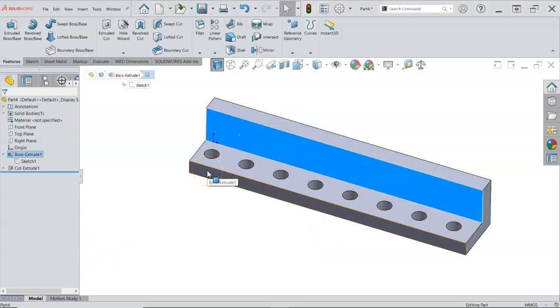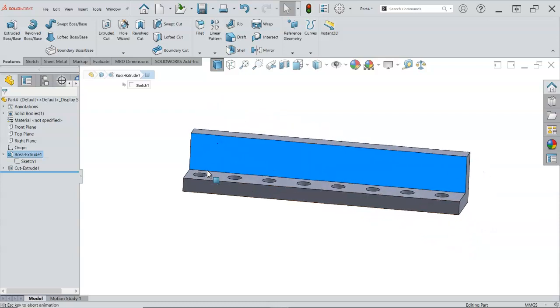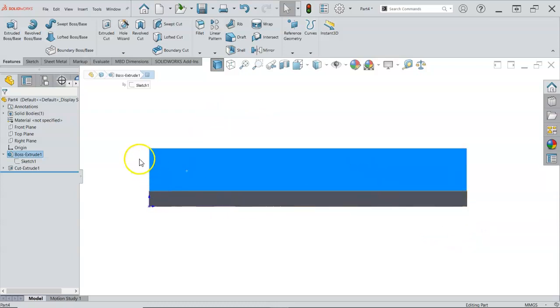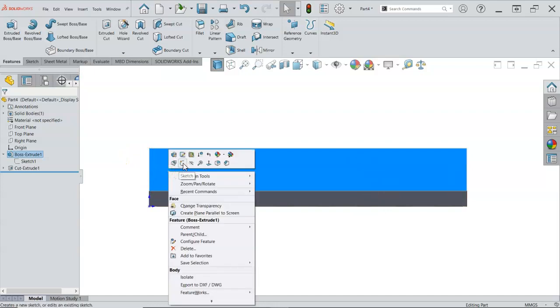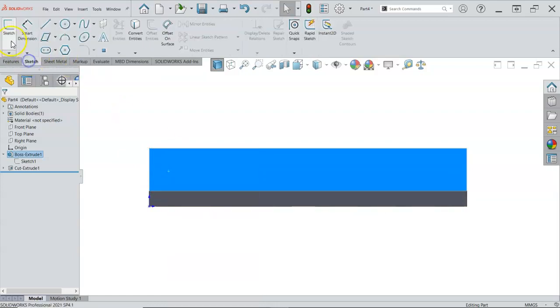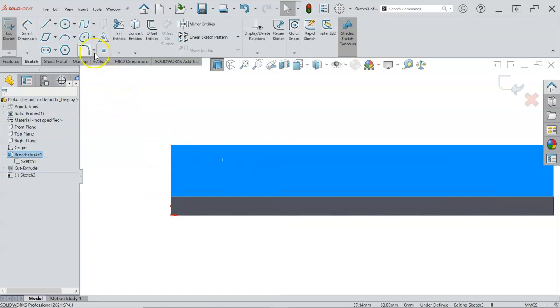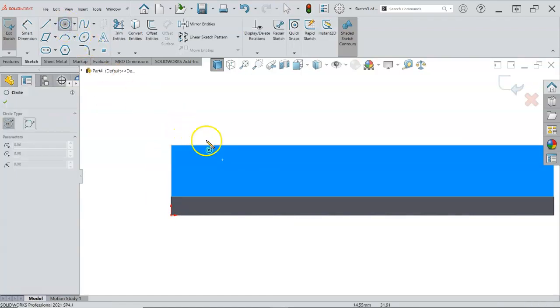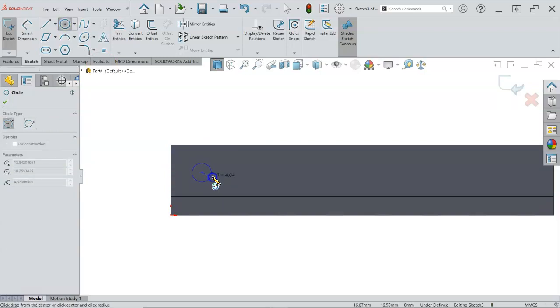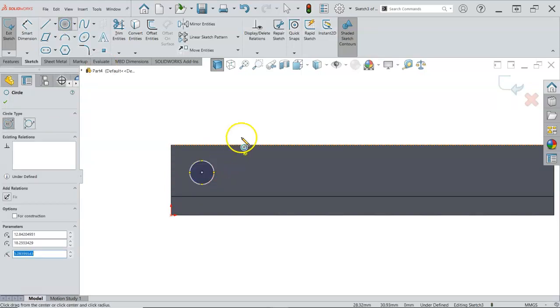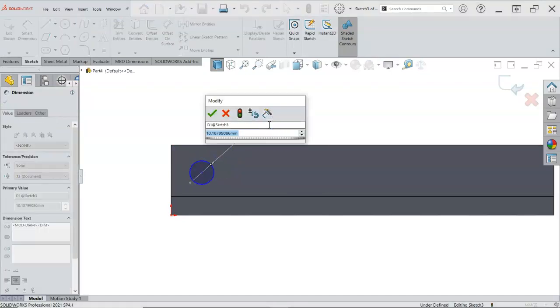Okay, so the two circles kind of have a mismatch. So let's go Control 8, which would also be the front view. And I'm going to right click again and sketch. Or again, you can come over and click sketch and pick your face, but I think it's easier just to get into the habit of right clicking and telling it to sketch on the face that you just picked. So those diameters are 10 millimeters. So that means the ones on the bottom could be as small as 6 millimeters, just kind of giving it a relative scale.